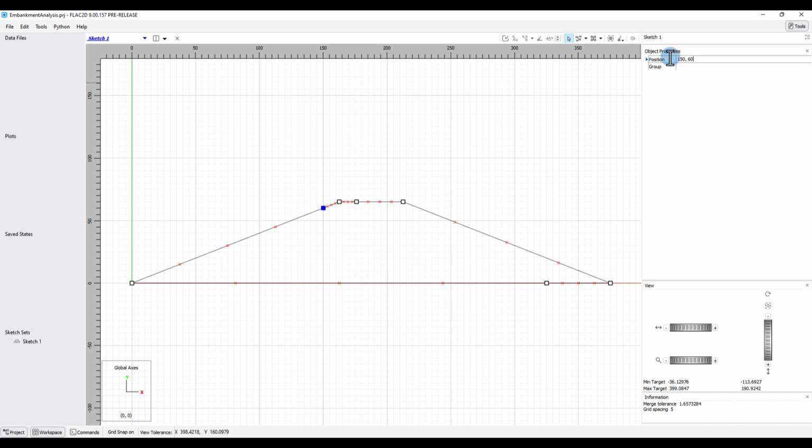For each edge type, now assign the group name and the zone size. Click the 7 edge types and then specify object properties discussed previously. It is now time to create the mesh for the domain.